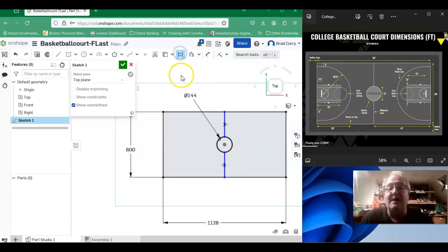What we're using here is the construction. So this is sketch new construction geometry, or convert existing sketch entities into construction geometry. So I'm going to turn the construction on and click on my line tool here. Now, when I draw this, pick up on the endpoint, and we're going to move this over.